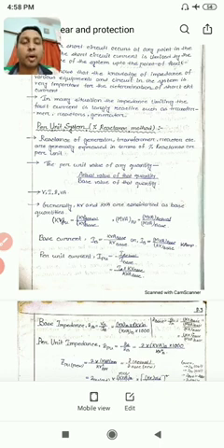In power systems also there are a large number of interconnected systems, and all the machines have their own, different ratings. When you interconnect them, we need a common base on which we can compare all these values, so that we can draw a single line diagram and utilize our normal circuit analysis in that network. In percentage we take a base of 100. Here per unit means we consider a base of one.